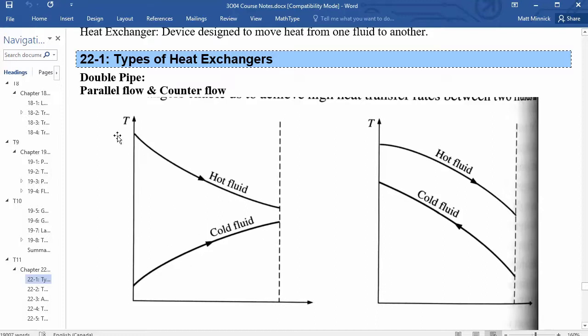So because of this exponential approach in this kind of heat exchanger, you've got more time at this lower temperature difference. So it's not as much temperature difference as you would get if you were to just average the total difference. That would be kind of assuming that we have a straight line. And you see from this curved approach here, this exponential approach, we have less temperature difference than we would have gotten through that straight line. Like the straight line fits from here to there, and there to there would have a larger difference on average than these ones. Okay.